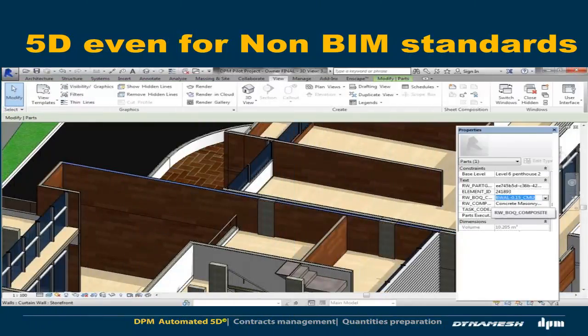However, and in certain cases, a BIM type needs to be allocated to different contracts or requires different prices for its sub-elements. This fact might be caused by the way the designer modeled the element, or because the management team decided to separate certain phases of the designed element into different prices, as in supply-install contracts. The Automated 5D system solved this dilemma by allowing the engineering team to divide a type into subtypes.